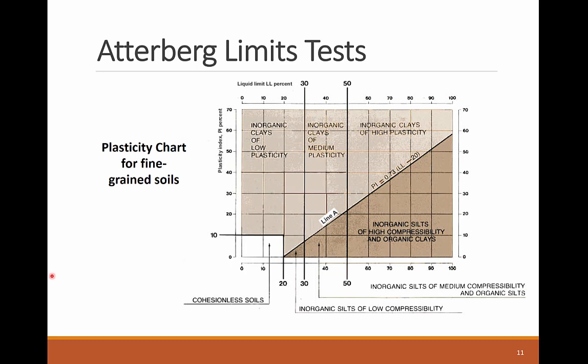We can make the following observations from the plasticity chart shown here. As the liquid limit of soils increases, the clay plasticity and soil compressibility increase. You can see here with these different categories, the plasticity increases moving to the right.